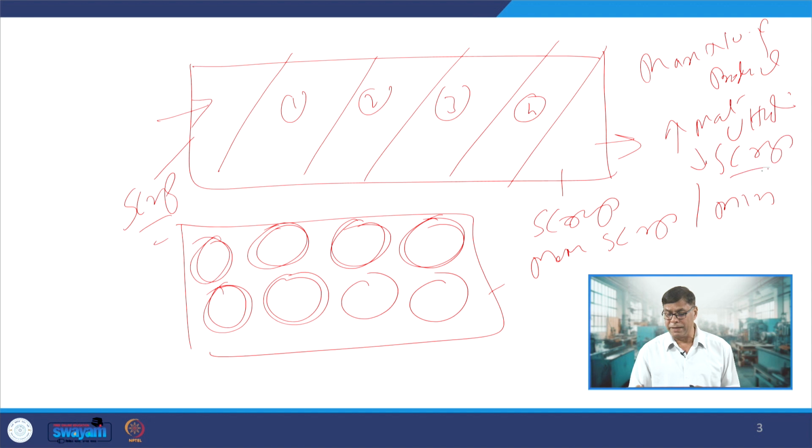This is one of the main ideas behind the layout design, apart from other aspects like how complex or how simple the die design will be, what press capacity is available, in which direction the samples will be cut, what the direction of the burr will be, and what kind of stock material is being used.